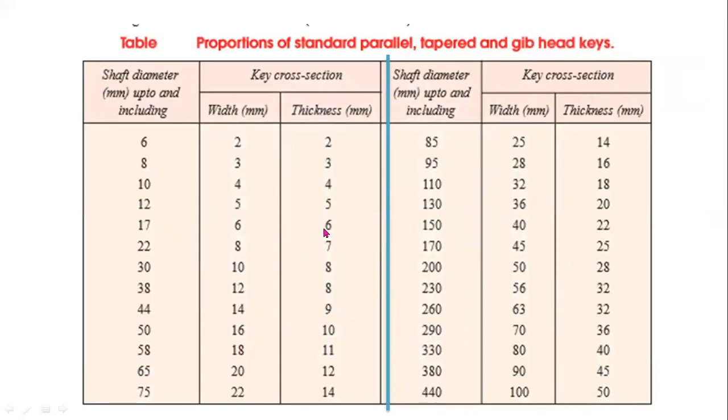These are the standard sizes of keys. For design of keys, we are using this table for selecting the standard width and thickness. Standard width and thickness of the key corresponding to shaft diameters. These are the shaft diameters, and these are the corresponding width and thickness of the key.